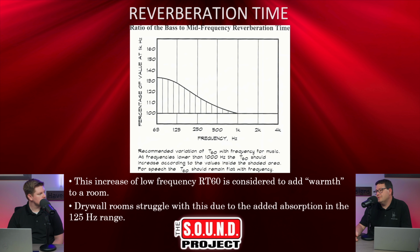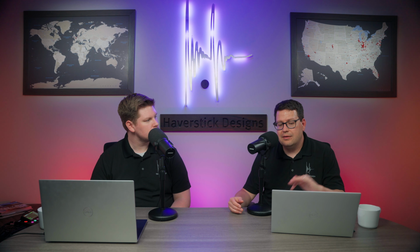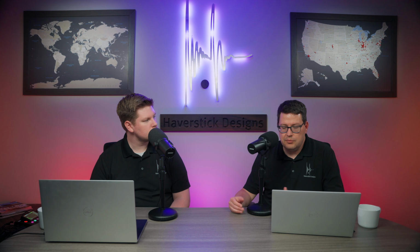That is the reason that orchestra halls use materials like concrete and granite and limestone, or just things that are very hard and rigid, because you won't see drywall in there. Any surface that needed to be drywall is usually plaster instead, because plaster doesn't flex like drywall does. That's in order to get this bass ratio where we want it to be, to make it a lot more musical in there.